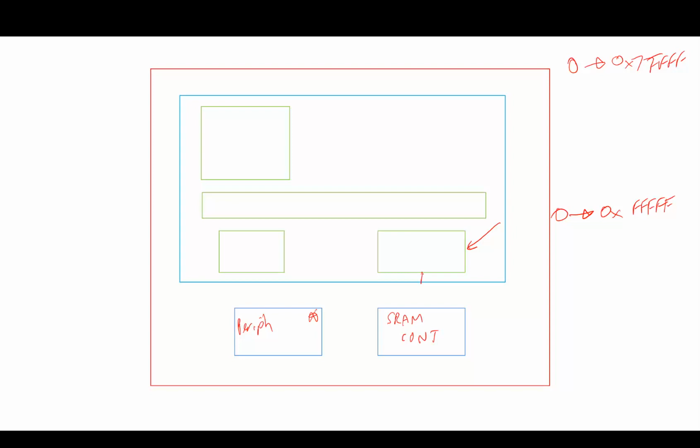And now the connection to the external bus bridge needs to be split. There will be signals that need to go to both of them. Some of them will just directly go to both, but for others there's only one input. For example, the acknowledge and read data, there is only one input for each of those back into the bus bridge.